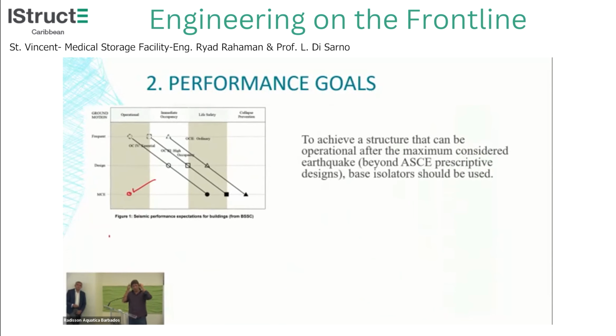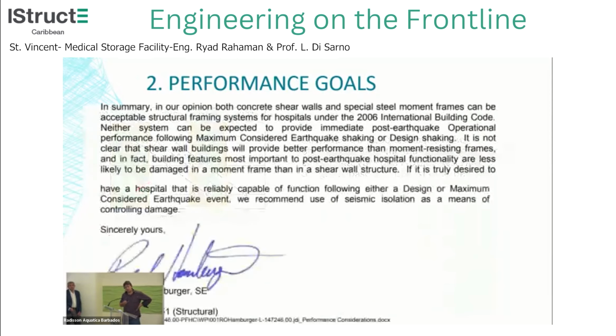So what should we be going for? This is frequent earthquakes, design earthquakes, MCE earthquakes, different return periods. We really need to be building an essential facility that can perform up to here, operational after a maximum considered event. We think base isolators should be used. Well, Professor Luigi and I think so.